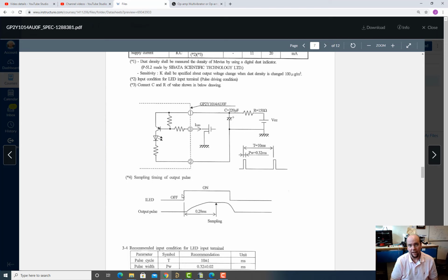We're trying to do an entirely analog circuit though, and so we're going to have to find some workarounds around this. So the goal of this video is going to be to, one, get the sharp sensor down, get it powered with this weird RC filter, and then two, create op-amp circuits that will generate a series of pulses that can be used to excite this thing, and then also have a circuit that detects the peak.